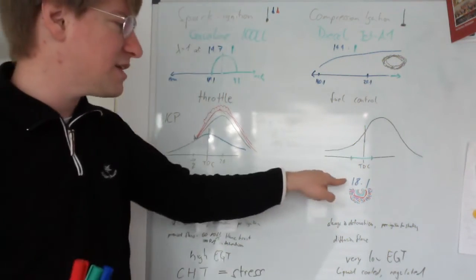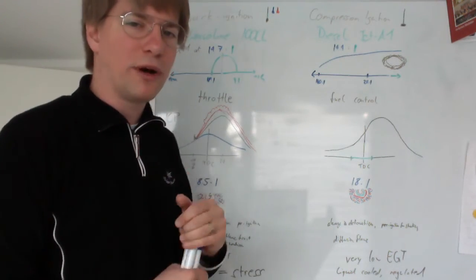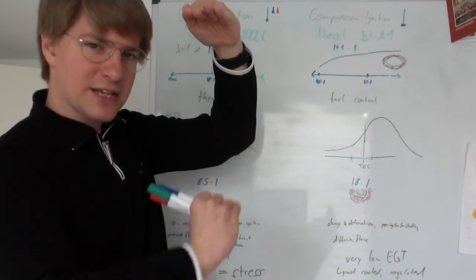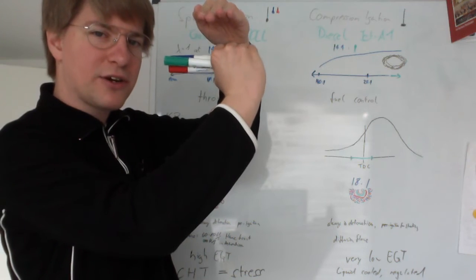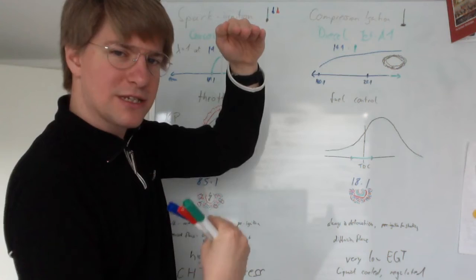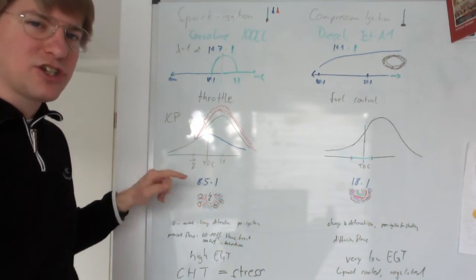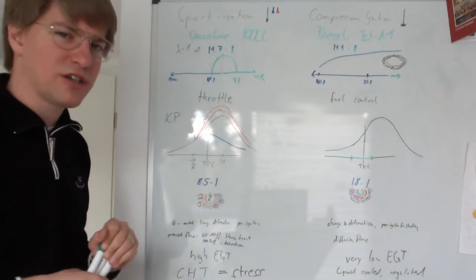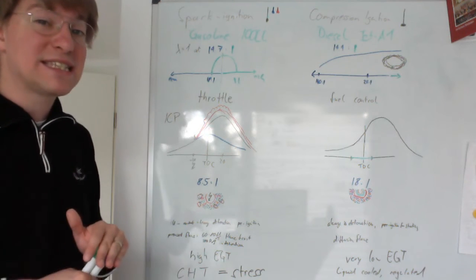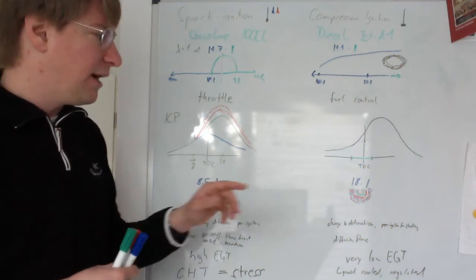In order to achieve this, we need to run the engine at a very high compression, typically about an 18:1 compression ratio. So the volume of the cylinder at bottom dead center versus the combustion chamber volume at top dead center is like 18 times bigger when the piston is down here than when it is up here. For comparison with the gasoline engine, in aircraft engines we are typically talking of only an 8.5:1 compression ratio, or even only a 7.5:1 compression ratio with supercharged engines.